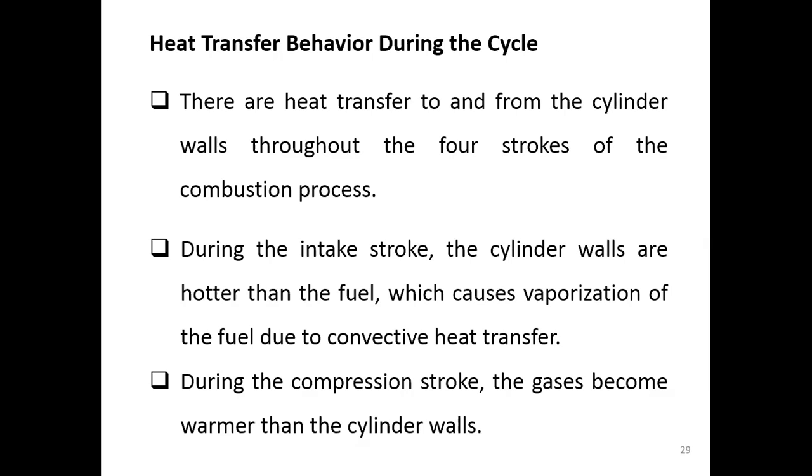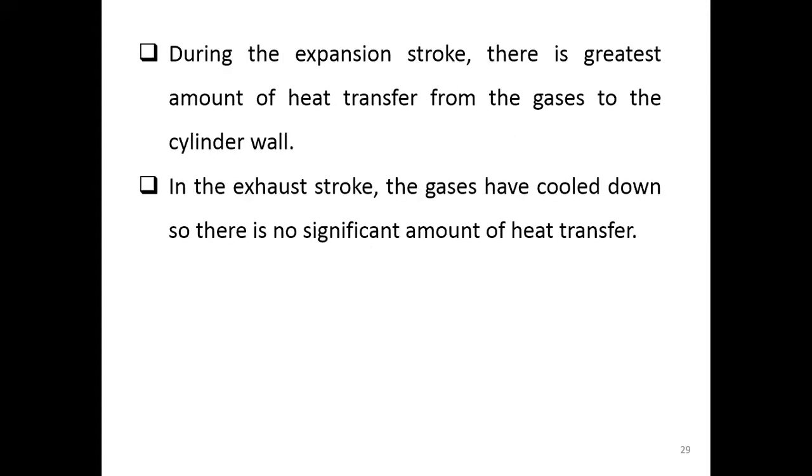We have heat transfer happen. During the intake stroke, the cylinder wall is hotter than the fuel, so vaporization of the fuel happens due to convective heat transfer. During compression, the gas becomes warmer than the cylinder wall, so we have heat transfer through the wall.